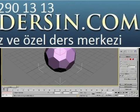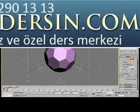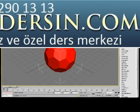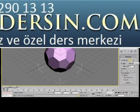Go over to the Modify list and we'll choose Edge. Select all the edges. Let's scroll down and click on Split. Let's choose the polygon mode. Select all the polygons. We'll go back to the Modify list and we're going to choose Tessellate. Under Parameters Operate On, we're going to choose Polygons. And we'll change the iteration to 2.